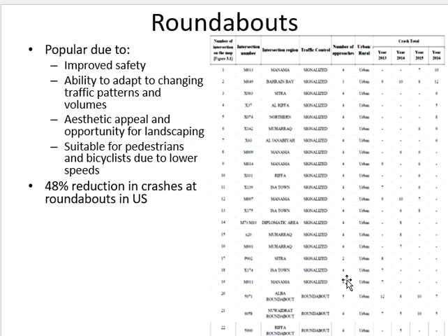You have to adjust it yourself. If the volume is higher from one direction, you have to adjust the signal timing for that direction. If you put a stop sign, again, that sign is fixed. You cannot take it away. Like, I will come in the evening and take it away. It cannot happen. So you have to keep in mind that the control device which you are using has to work permanently for all traffic situations.